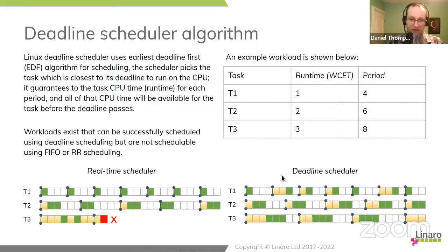The other difference, of course, is that T1 is experiencing quite substantial jitter. So the delay before it does its processing varies between 0, 1, and 2 milliseconds. And that's okay, because that's within specification. Right? We're about as fast as specified. So although we do observe significant jitter in T1's timing, there was no requirement that we had to avoid jitter in T1. If we wanted to avoid jitter in T1, we'd have to reduce the deadline. So the deadline is what you can use to avoid jitter.